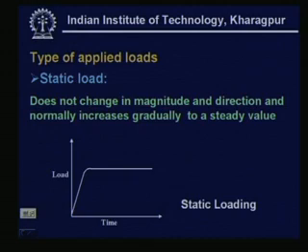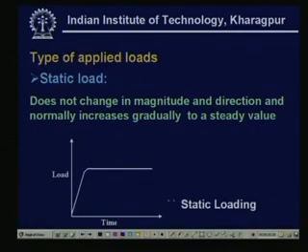See, obviously the first one is what we call a static load, where the load does not change in magnitude and direction and normally increases gradually to a steady value. Even though it is not mentioned here, we can consider that the point of application of the load is also not changing. What I mean is, if there is a material and a load is acting this way, these are the points of application, and with time the point of application of the load P is also not changing.